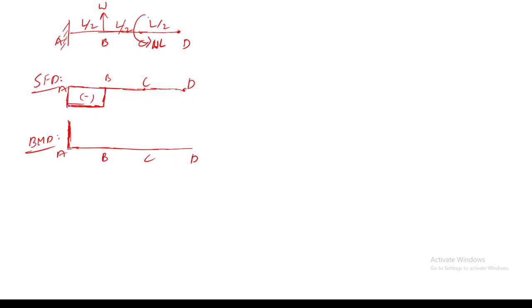See, for example, this moment is of value WL, right? So what will be the reaction moment at point A? WL plus WL by 2. Yes, so it will be 3WL by 2. Okay?